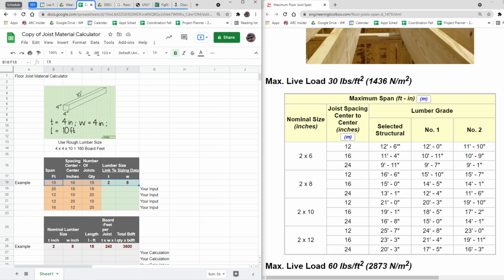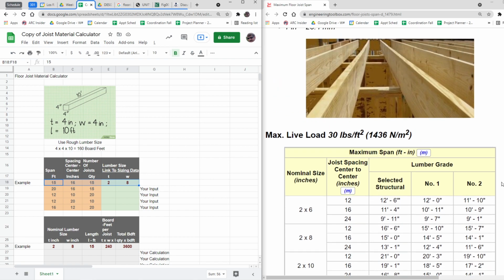Okay, so this gets complex. That's why we have architects and designers. Really cool. And that's why your detail drawing doesn't specify all this stuff. It just shows you how it's going to go together. A detailed drawing would show that this is sitting on top of this, and that there's a hanger way down there at the end, and you would just specify this size in a note, but it wouldn't have to be drawn to scale.